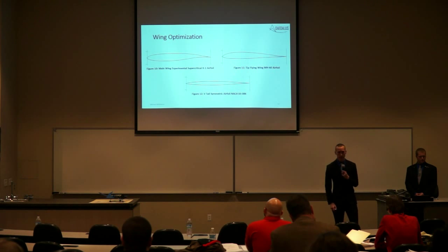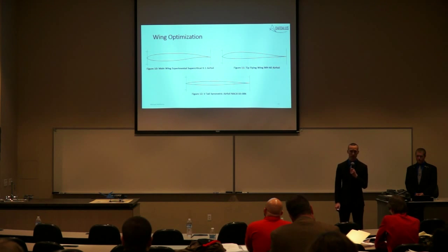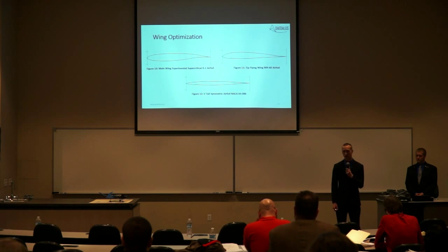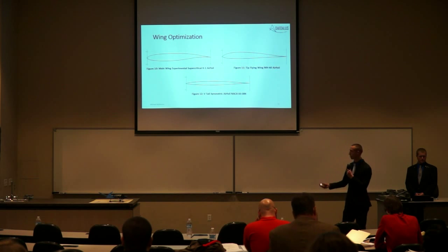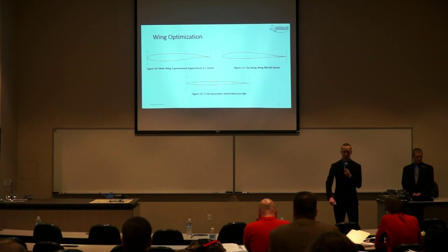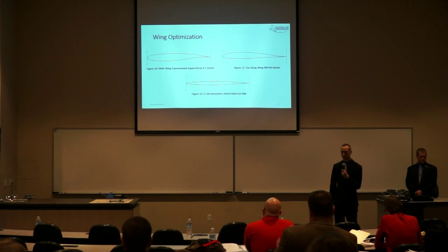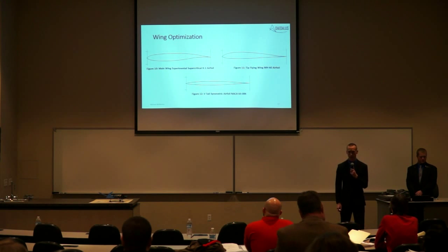This created two issues, one of which was that we were trying to cruise at a transonic airspeed, which is between Mach 0.75 and Mach 1, and that would require us using a supercritical airfoil, similar to that in the top left. And with the high sweep and shallow chord of the wing, we decided to use a flying wing, as that would have an inherent resistance to twist.